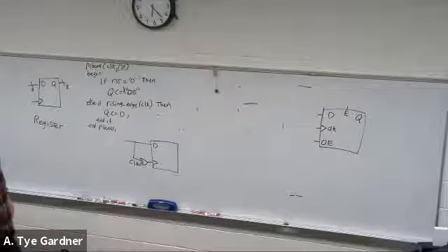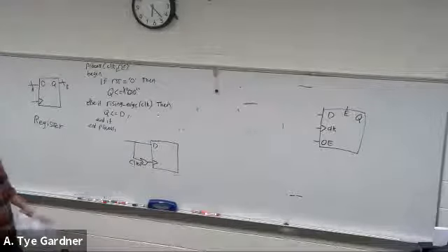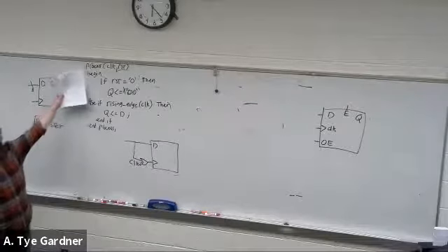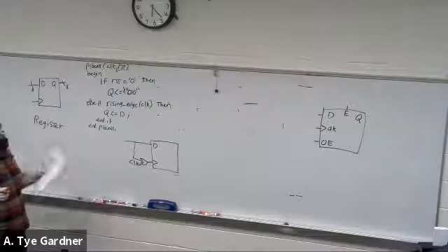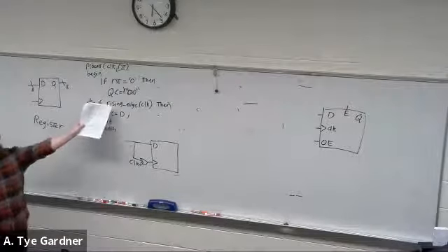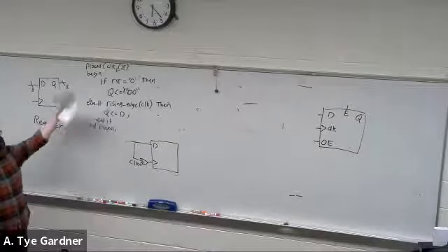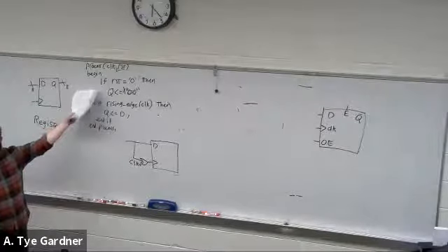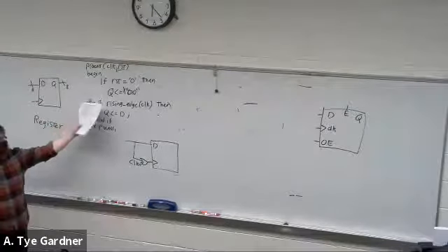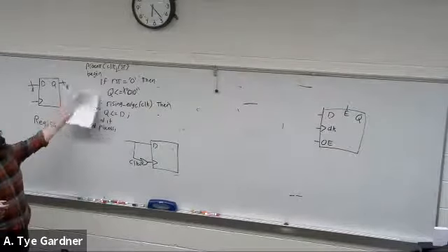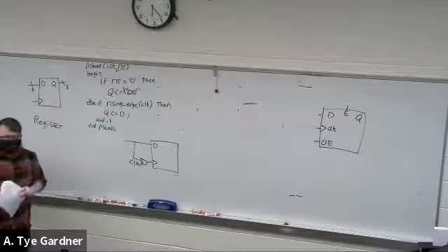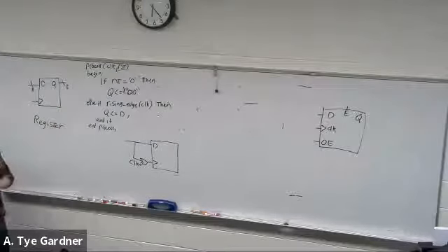Other rule that I have in my notes just to highlight, anytime you're inside of a process, limit yourself to one and only one rising or falling edge statement. If you need it, you can actually have multiple processes in one VHDL file. That's fine, but don't put multiple rising edge inside of the same process. That will cause you really difficult to track down errors.